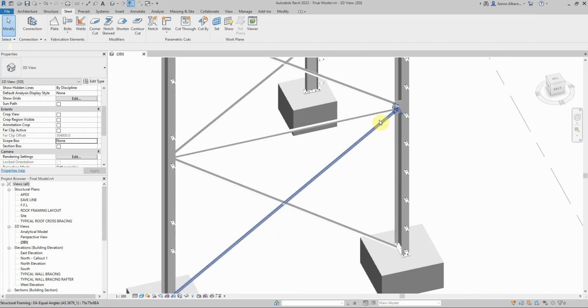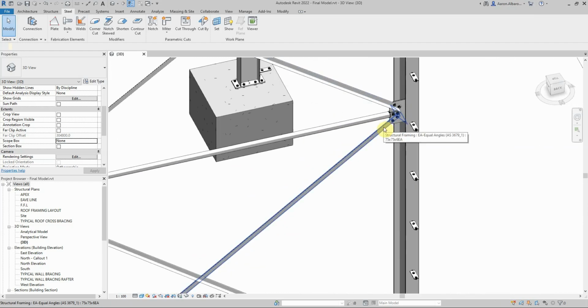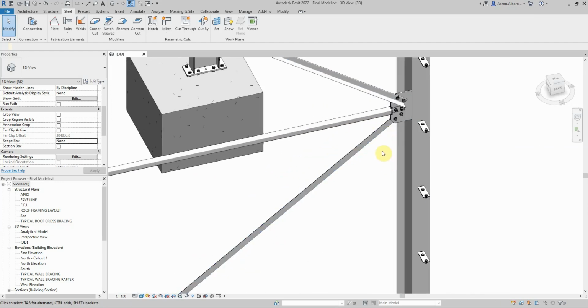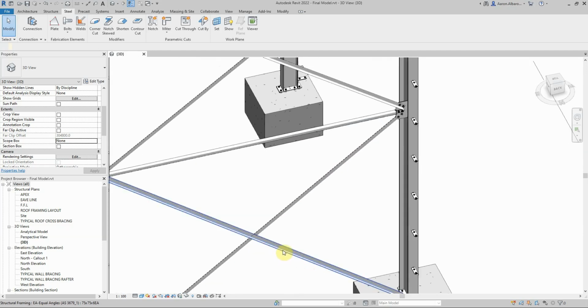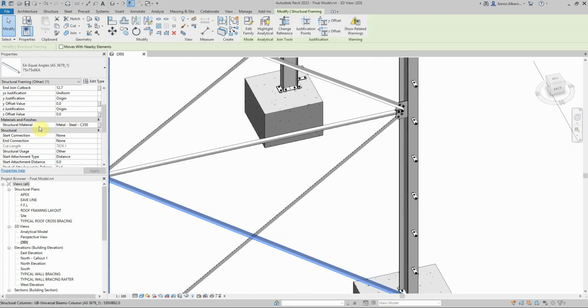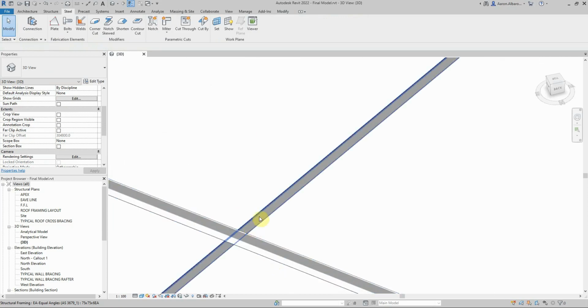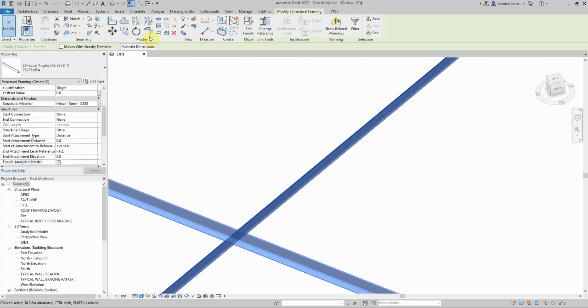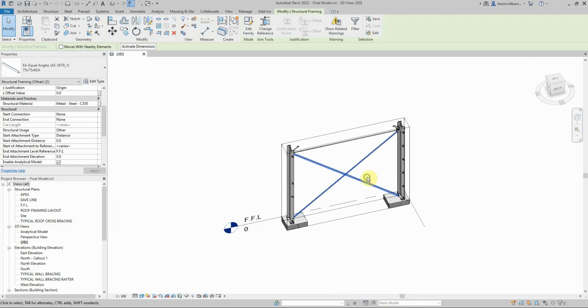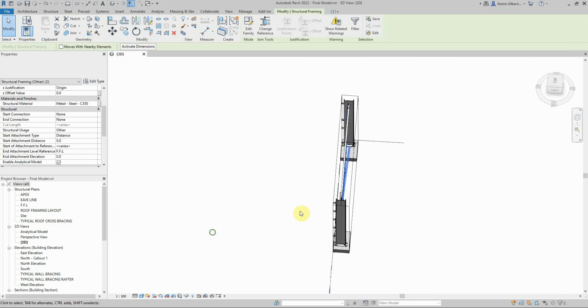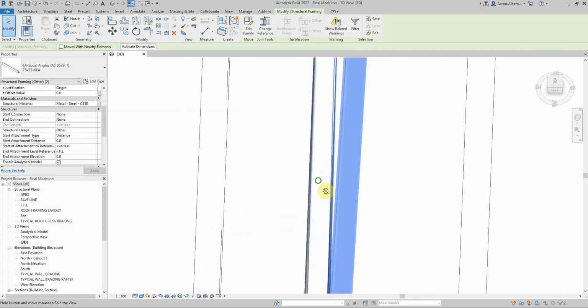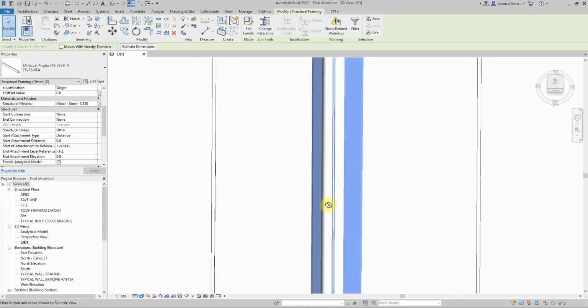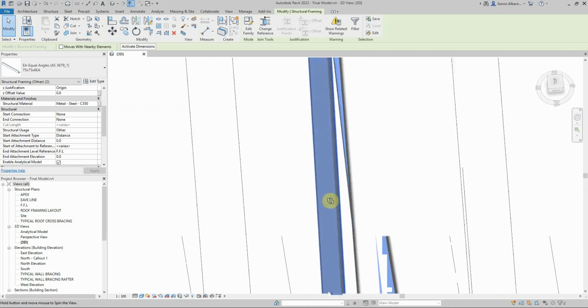Now if you look at it here, because I offset that angle by 35 millimeters that way and this angle by 20 millimeters this way, so by offsetting this small angle again the same as the top one by 20 millimeters, negative 20. If you look at them, these two angles, they don't intersect anymore. So if we look at them, these two angles here, there's a small gap between them, and that's what we want, because we don't want the two angles to be rubbing against each other. Okay.